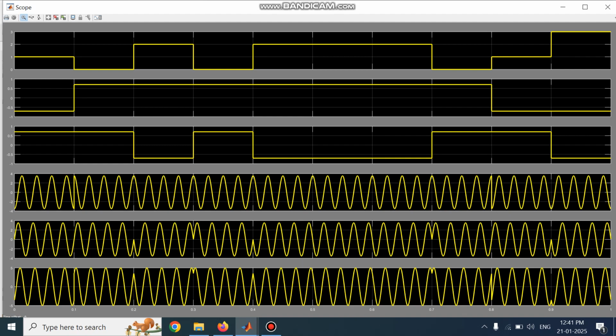Next integer is 2. It is represented as 1, 0, and the corresponding phase is 45 degree. Next integer is again 2. It is represented as 1, 0. The corresponding phase is 45 degree. And next integer, here it is changed. Integer is 0. The corresponding gray code is 1, 1. Odd is 1, even is 1. The phase value is 315 degree. Next integer is 1. The corresponding gray code is 0, 1. And the phase value is 5 pi by 4 or 225 degree.